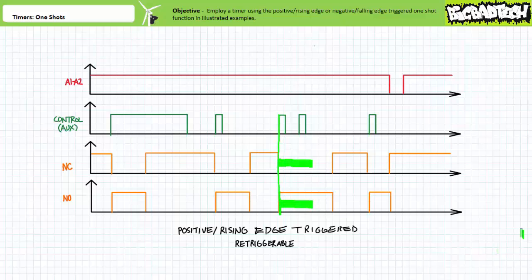When the retriggerable positive edge OneShot experiences a triggering event, followed by another triggering event during an ongoing OneShot. Ordinarily, the OneShot would execute a 5-second OneShot after the receipt of the first positive edge. The retriggerable OneShot, however, instead of ignoring the additional input during the ongoing OneShot, basically dishes out 5 more seconds of OneShot, as we'd expect.